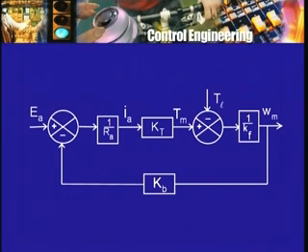From that, subtracting the load torque leaves the frictional torque, so that divided by Kf produces the motor speed omega m. But I should not forget about those two subtractions that took place. One of them took place here, and that is the line I have drawn from omega m to Ea, and I should of course put Kb there, not a direct line but Kb.